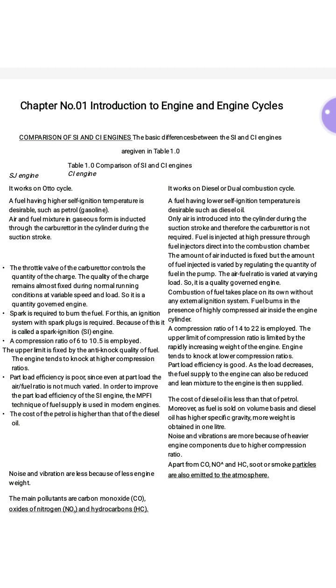Next, the throttle valve of the carburetor controls the quantity of charge. The quality of charge remains almost fixed during normal running at variable speed and load. So it is a quantity governed engine.